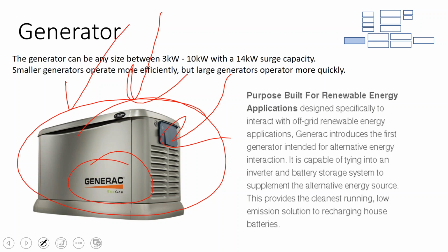The only thing I have to say is when you get into lower-end off-grid designs with generators, not all generators can be turned off. Some of them can only be auto started rather than auto off. And so there are solar designers who say, you know what, I'm going to have a small generator, and if my battery voltage gets low, I'm going to just turn that on. But then if I'm having a more severe weather event, I'll have a larger generator with a spare tank reserve just for risk mitigation. When we talk about inverter selection, that might become a little more clear.